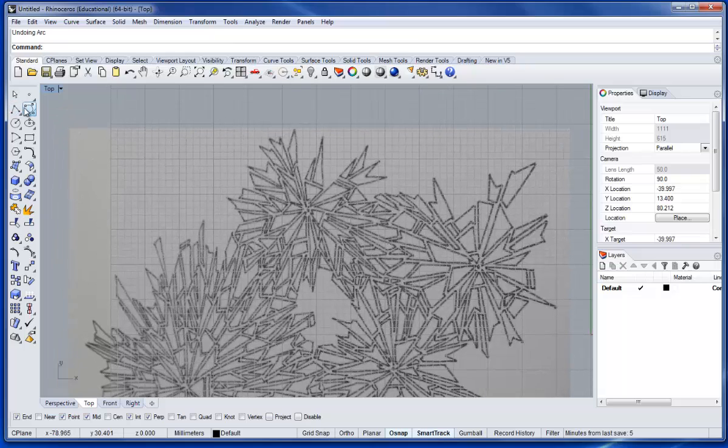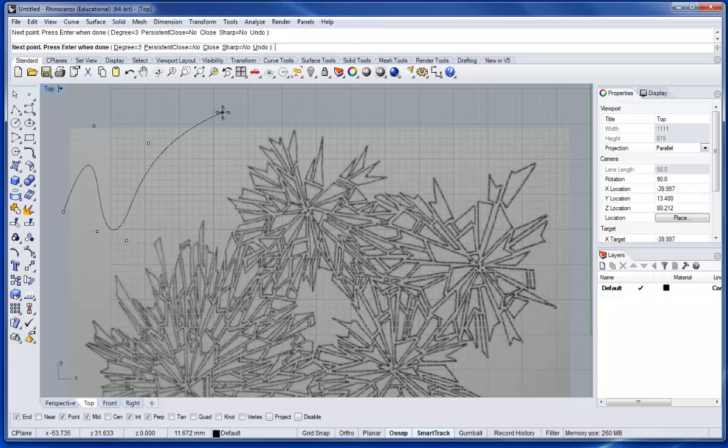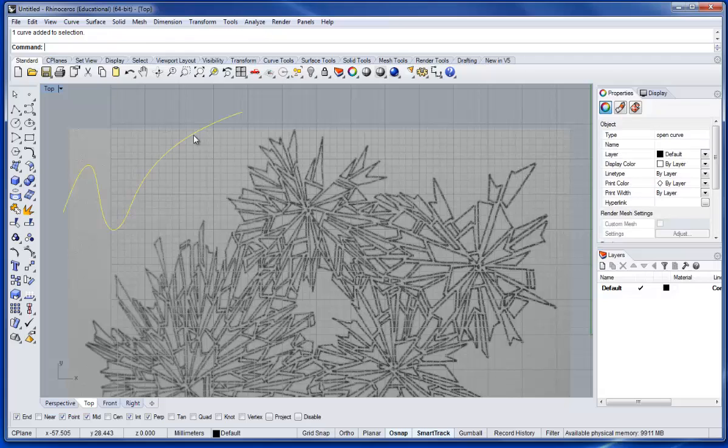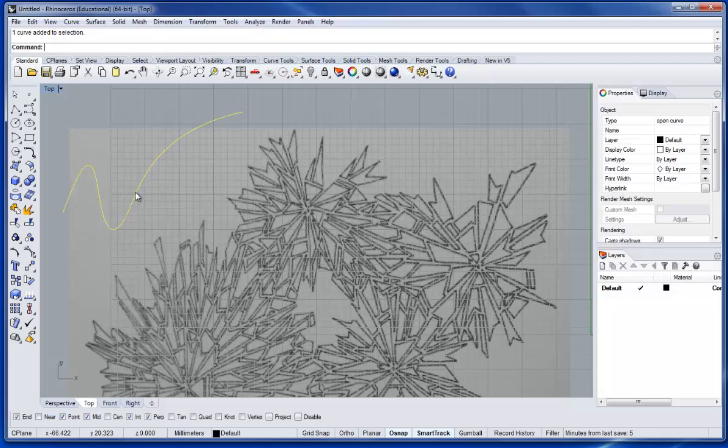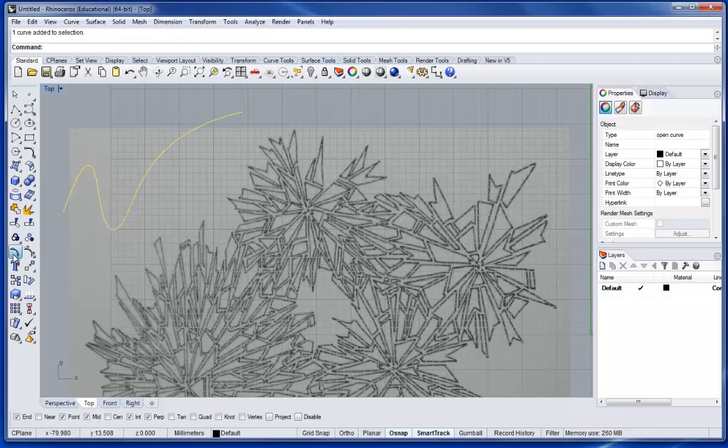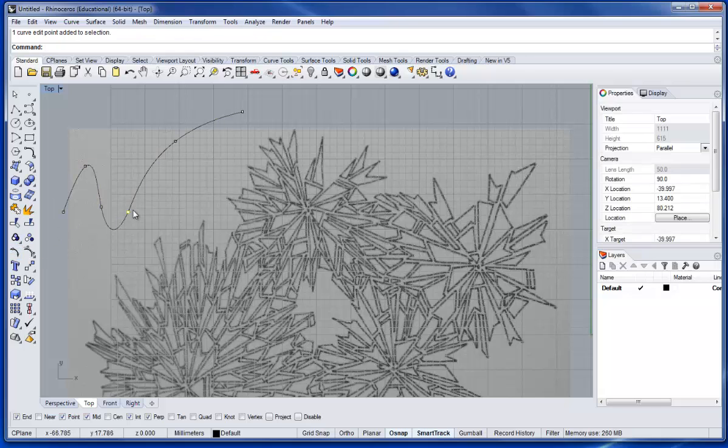And then you have 3-degree curves, which are essentially based on mathematics and weighted knots. So they're Bezier curves here, and I can toggle those on and off. And so you can see the weights in here, the knots can be manipulated around and shifted. Another way, if I hit escape twice, I can also turn on the actual edit points on the curve here and start to manipulate those around as well. So those are 2 ways you can start to edit those curves.